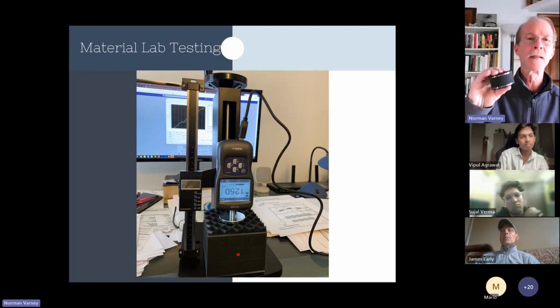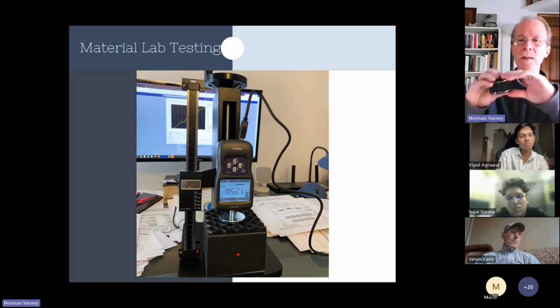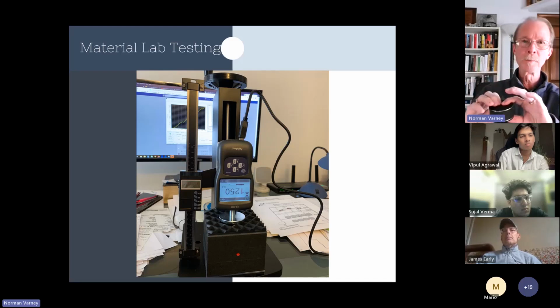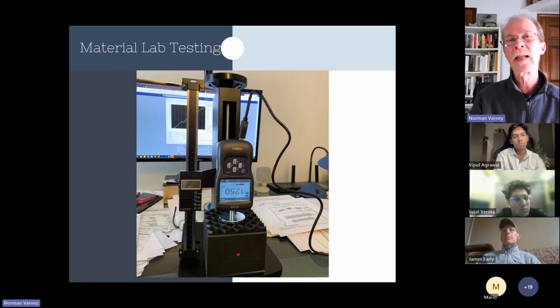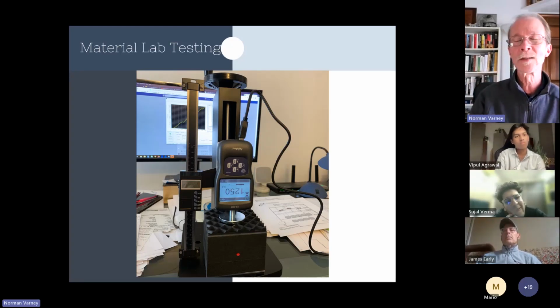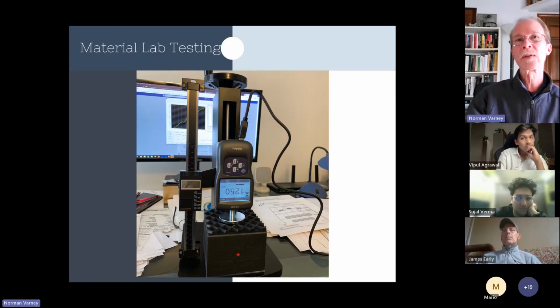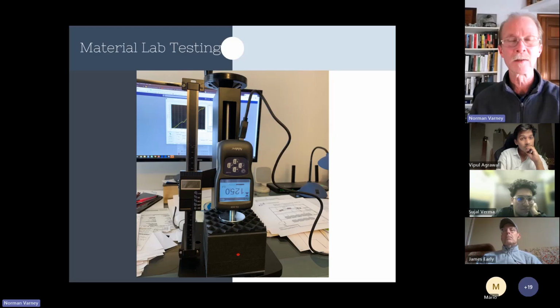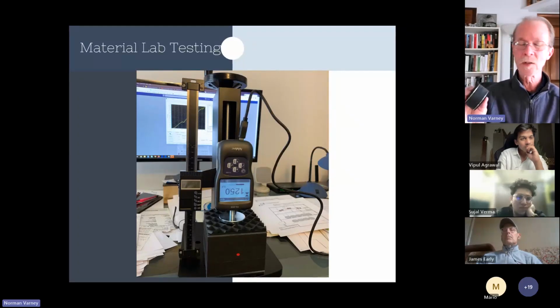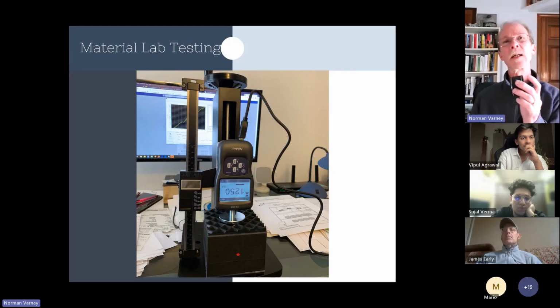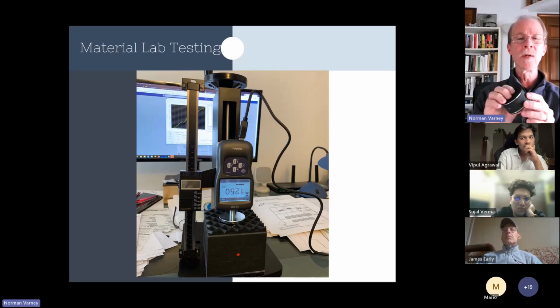When we designed this, all the products that we make, regardless of the size or the load, are going to be designed to have a natural resonant frequency of 3.4 hertz, and they become effective right at 5 hertz on up. Conservatively, they'll mitigate 90% of the energy from 5 hertz on up. To me, this acoustical product is like the least expensive product we sell. It is the most effective product that we sell from so many points of view.